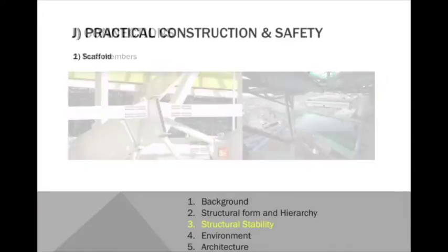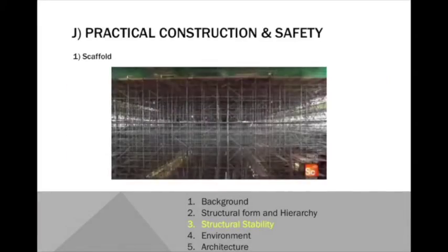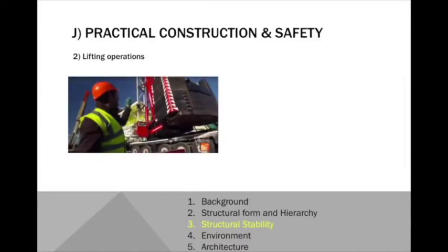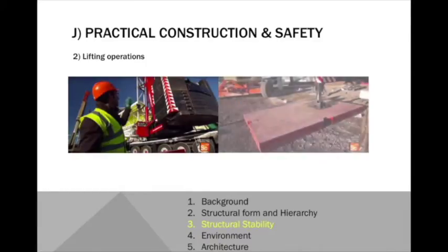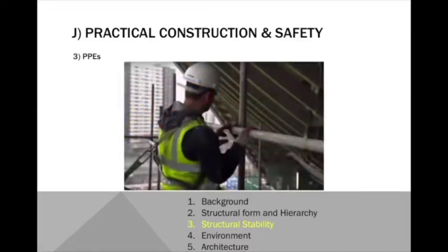In order to build this single-span roof, scaffolds resting on the ground were used during the construction. This hindered the construction of the swimming pool. Due to the time limit, the construction of roof and pool must be operated at the same time, so builders had to build and remove the scaffold every day, which is not practical. The working radius was only about 100 foot because the stands will be built between the river nearby and the aquatic center. The chassis of the temporary stand were heavy due to the large span. Thus, more balanced load was needed, and this doubled load on the ground.